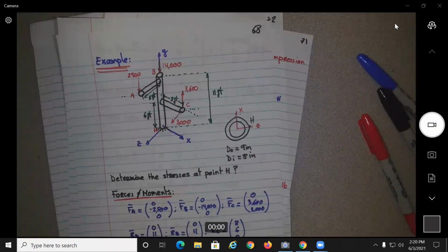What would be the way to do that? We're not going to do it, but why have I been giving you complicated loads for a beam? Let's say if you wanted to replace this just by one beam, what could you do? You could replace this by one beam, but then at this point you will have to add an axial force plus the moment created by this, no? And you could eliminate this member over here. At the top, you could do the same thing. You could put the force plus the moment created over here, no? Yeah? And now you could just study the stresses along this one due to that load distribution. It should give you the same result.